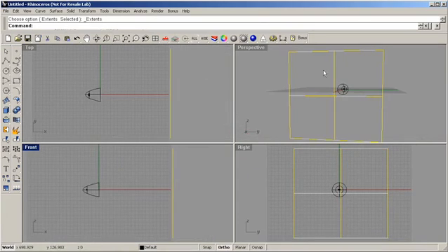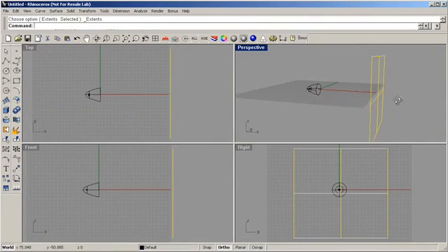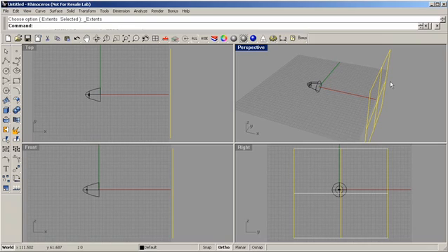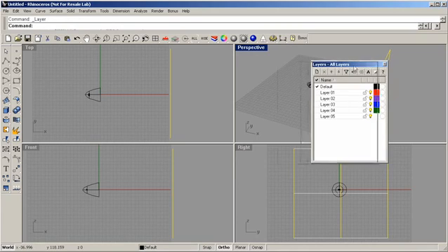I'm going to do an auto zoom here, and that's what the system looks like. Now at this point we can export geometry over into ASAP, define and assign optical properties, and run the ray trace. However, for complex CAD models, it's much easier to do that if objects are layered according to their optical properties. Just as an example, even though this is a very simple system, I'm going to show how that's done in Rhino. We're going to go up here to the Edit Layer dialog box,